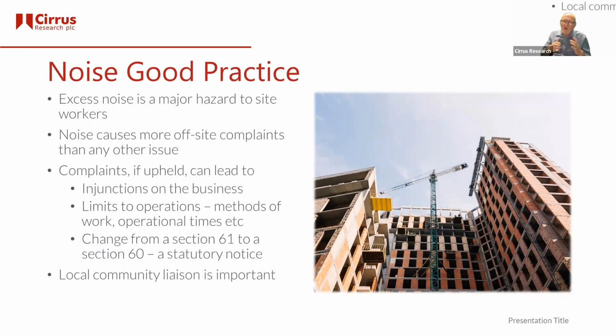And what's important with all of these construction works is that liaison with the local community is vitally important. Letting people know what's happening, how long you're going to be there, what the likely impacts in that local environment are on those people, and keeping that community liaison going, irrespective of any particular issues, will always help to minimise the complaints and the impact on the local community.